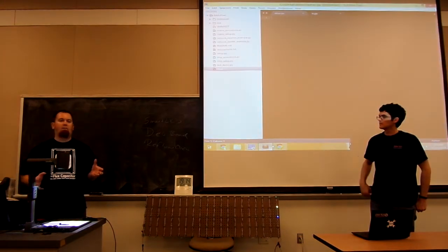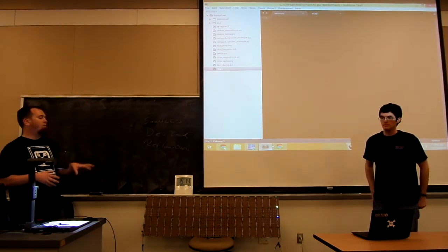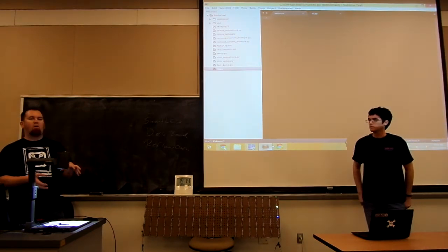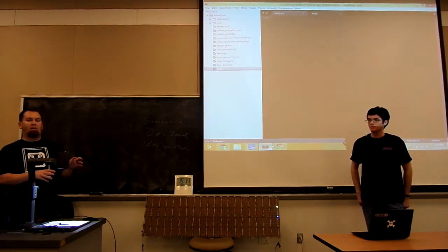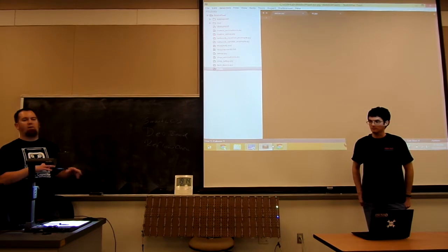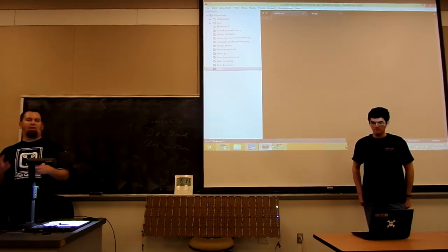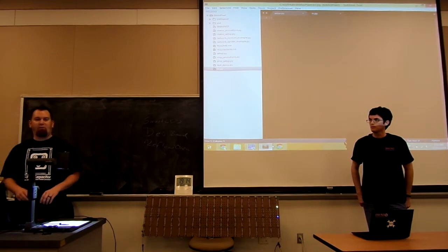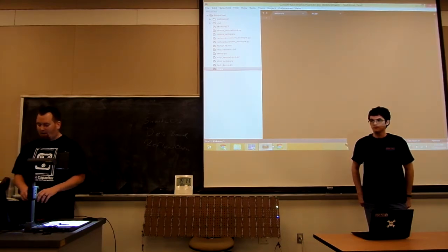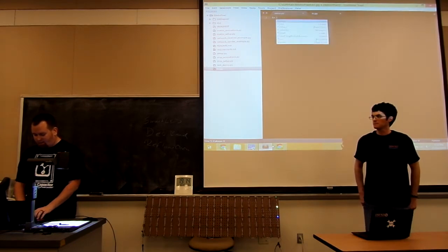We've also got an entire library that I've named BiblioPixel, which drives this, but also will drive these lights directly from a Raspberry Pi without it, should you really want to. Like pretty much anything that's SPI, it'll drive those. It won't do the NeoPixels, which is actually part of the reason why we designed the board in the first place. Technically, yes, you can drive it from a Raspberry Pi with some kernel kung fu, but I don't like doing that. It's dangerous.